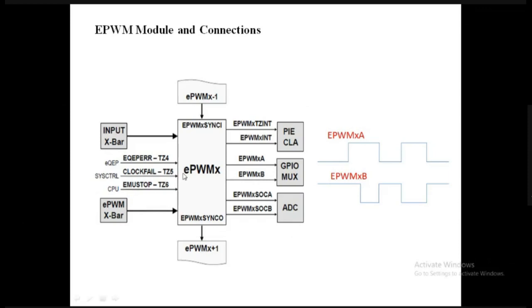So every module has its basic details. Okay, and it is not in a brief way. It is like you should understand it in an elaborate way in order to understand each and every module or submodule of this particular EPWM. So the output of this PWM, it can generate a start of conversion signal for ADC. ADC is an analog to digital converter and it is operated through a clock pulse only. So that clock is nothing but a start of conversion signal. So to generate that start of conversion signal, you can use EPWM.